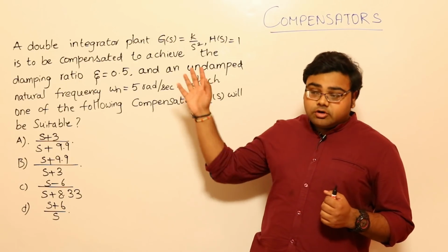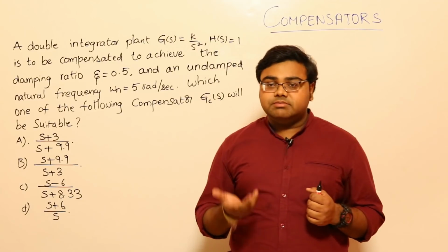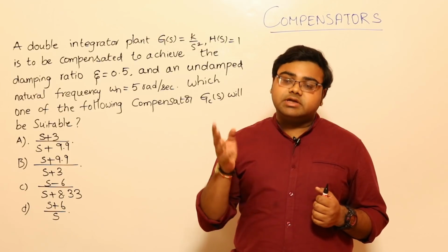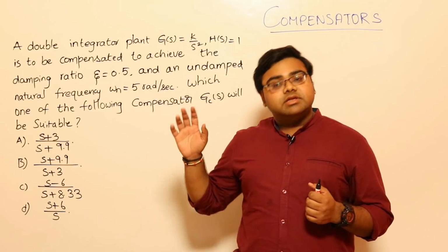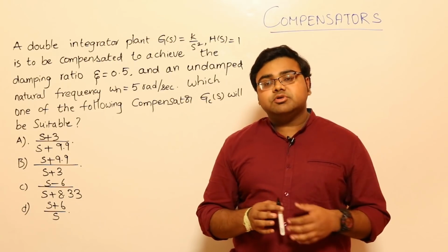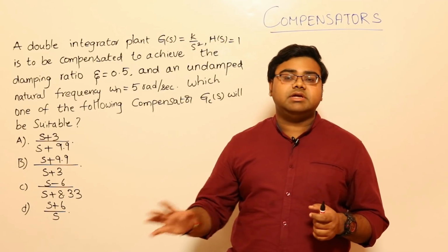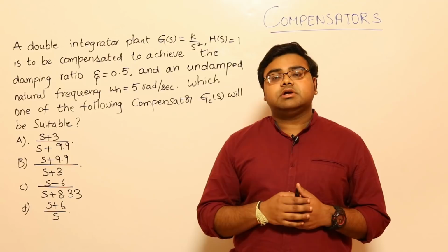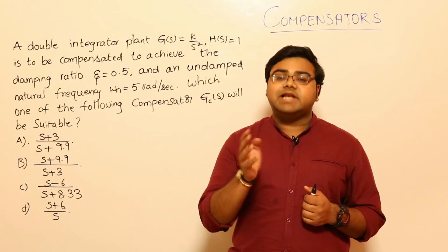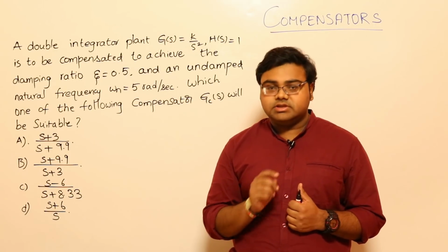Second, not just compensators, there is another topic called controllers also, where PID controllers and all come into the picture. Is there a relationship between compensators and controllers? The answer is yes. Some of the compensators will be equivalent to some controllers. Lag compensator will be equal to some controller, lead compensator will be equal to some controller, lag-lead will be equal to some other controller. Which is what? Again, confusion will come. Whether lead is like derivative controller, whether lag is like derivative controller, or vice versa. Confusion has again come.